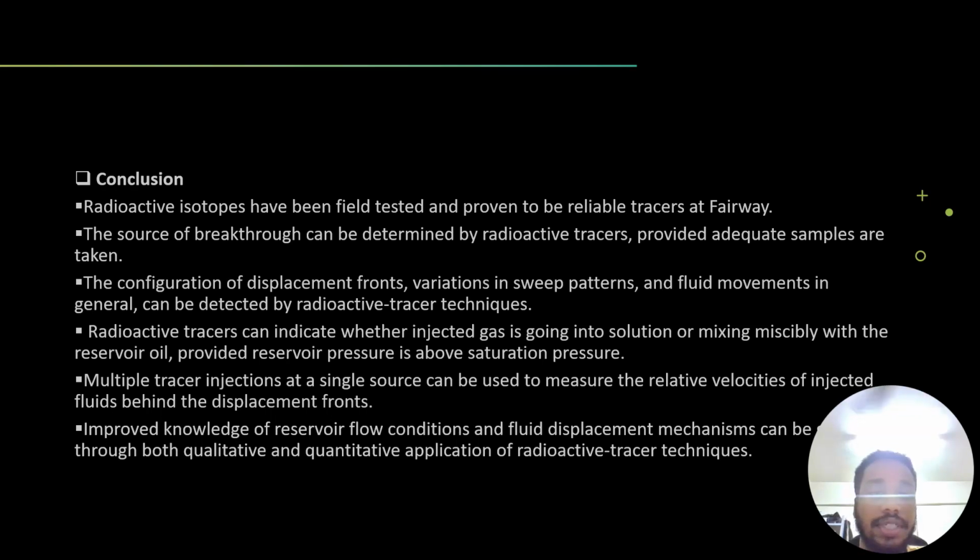Multiple tracer injections at a single source can be used to measure the relative velocity of injected fluids behind the displacement fronts. Improved knowledge of reservoir flow conditions and fluid displacement mechanisms can be gained through both qualitative and quantitative applications of radioactive tracer techniques.